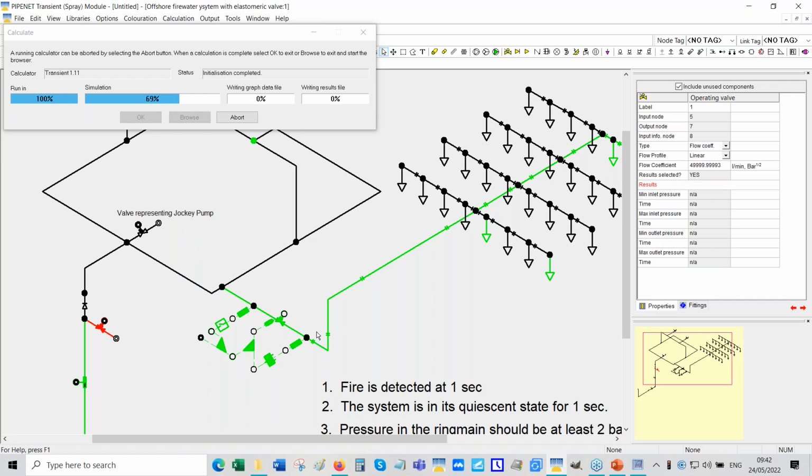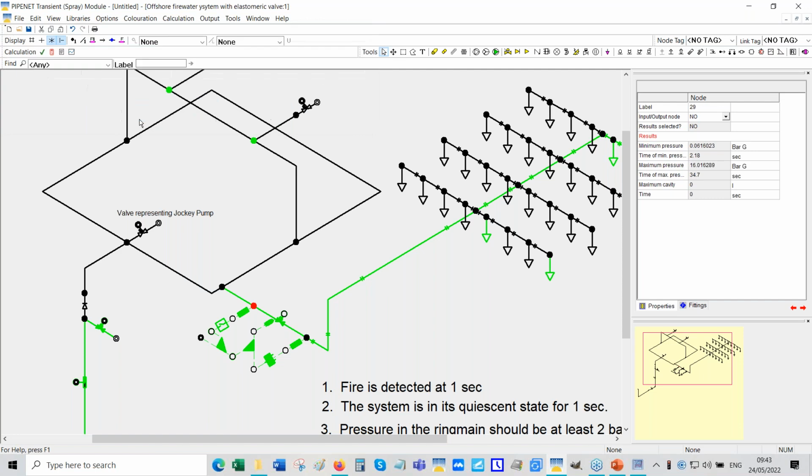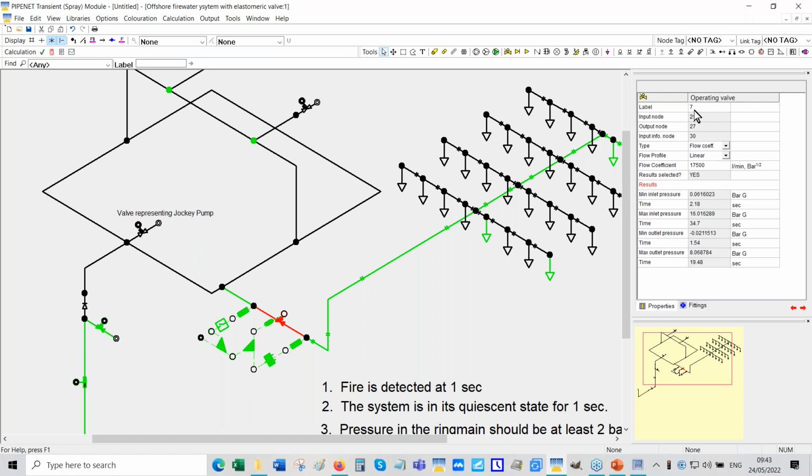Control systems are actually quite difficult, more difficult to model because of the feedback effect, that it is actually doing a lot of things because it's checking all the time that the pressure here is more than 2 bar. And then it's got to model the PID controller and then select the signal between these 2 and so on. So it's got a really hard work to do. We can look at the position of that valve. That's valve 7.